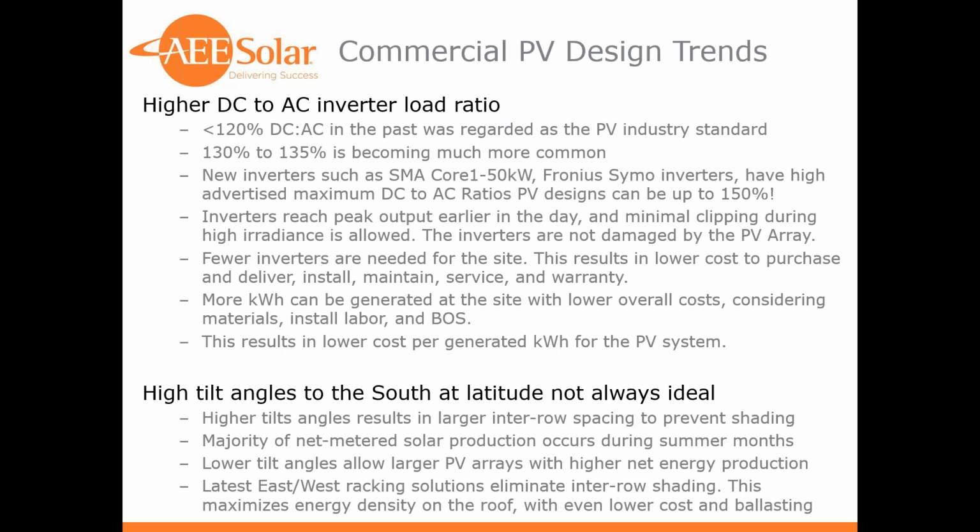Also, still seeing newer commercial installers who are used to doing residential mounts or ground mounts, and they want to tilt at extremely high angles to try to capture every single watt that the module possibly could capture, but not realizing that that gets rid of a lot of benefits for larger installs on commercial roofs.